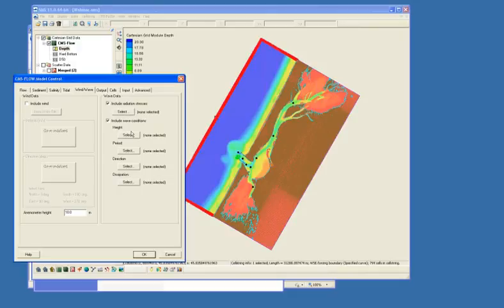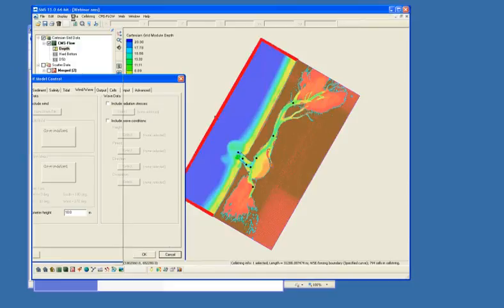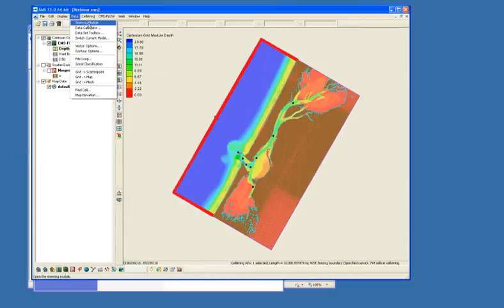I have a note here from Alex Sanchez, who's going to be giving the webinar next week, that the spatially variable winds will be covered next week. But as far as the wave data, normally this is not how we handle input of waves. We handle the waves through a feature called the steering module, which is under data, steering module.